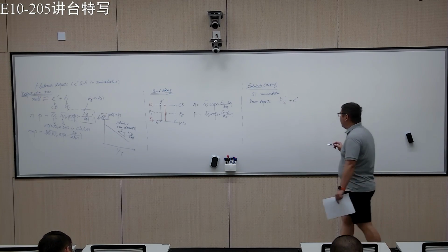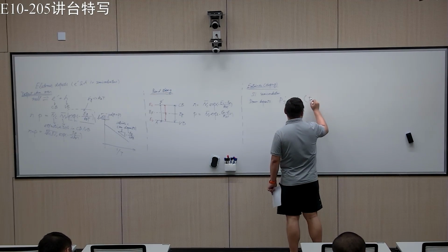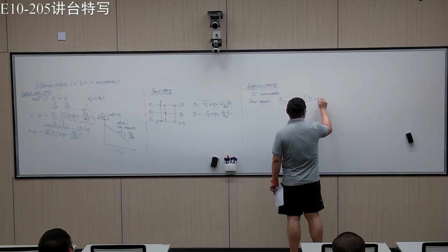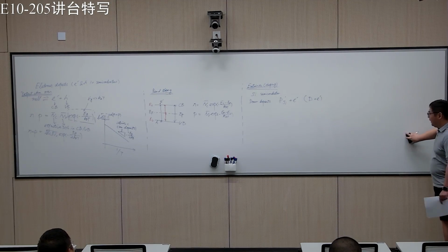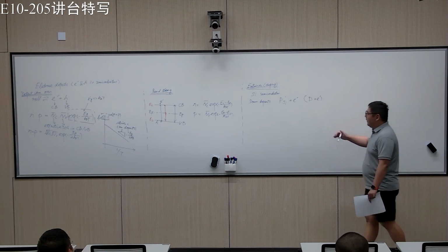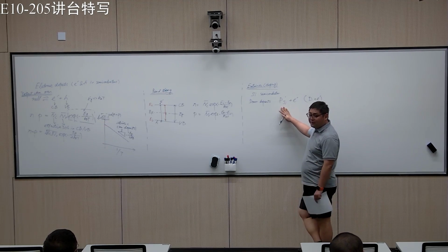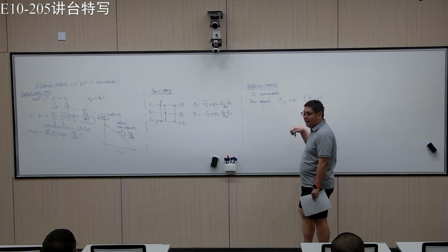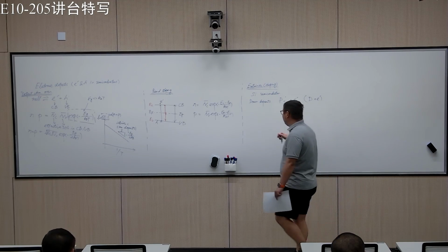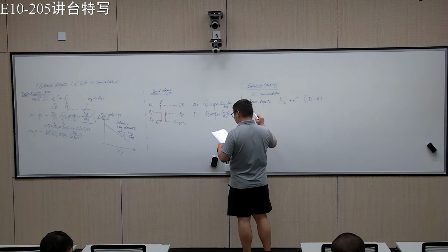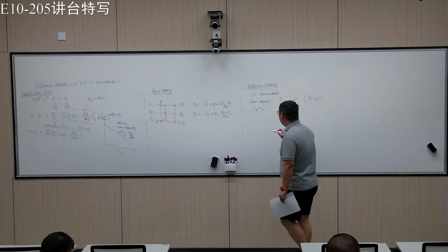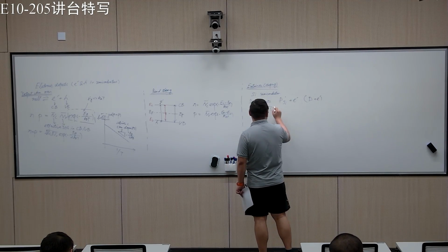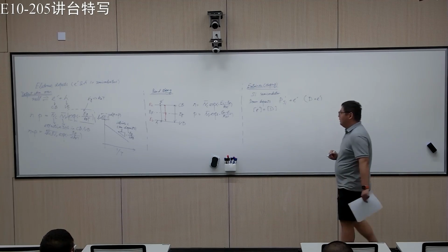Or in more general, you can write it as the dopant and an electron. So if we say every single phosphorus doped into silicon becomes positive and donates 1 electron, what we can simply write is that the number of electrons is essentially the same as the number of dopants.